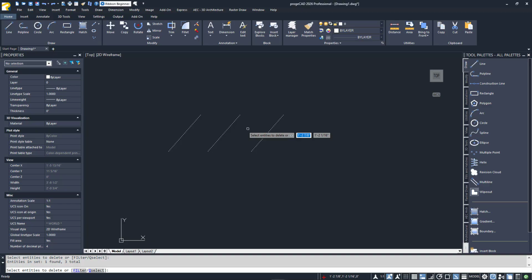An even faster way to toggle between removal and addition modes is with the Shift key instead of the R and A. Press it down during selection addition mode, and it will turn it into removal mode. Release the Shift key, and it will return to addition mode.